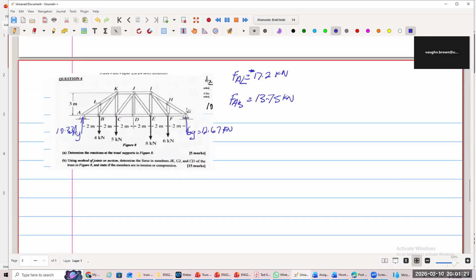So the joint that we are considering, I'm going to draw the joint now. The first statement you must say is, consider joint L, so everybody knows what you're doing. And then we stick a pin here and we draw it. So that is one, and the other one, AL, is this. The AL now is going into the joint, it's not coming out. If you put it into the joint, you can use it as positive.